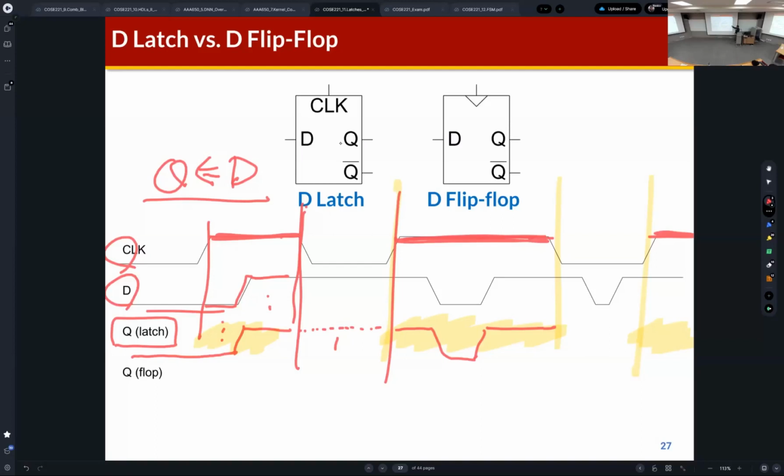So the latch becomes opaque. It just looks like memory. So Q is not changed during this period. And then this is just 1, and the output is just the same as the input. So you can understand that if the clock signal is 1, the output is just the same as the input to the latch. Otherwise, the output is just maintained. In this period, the input signal is changed, but the output is just maintained. So this is the behavior of the latch.